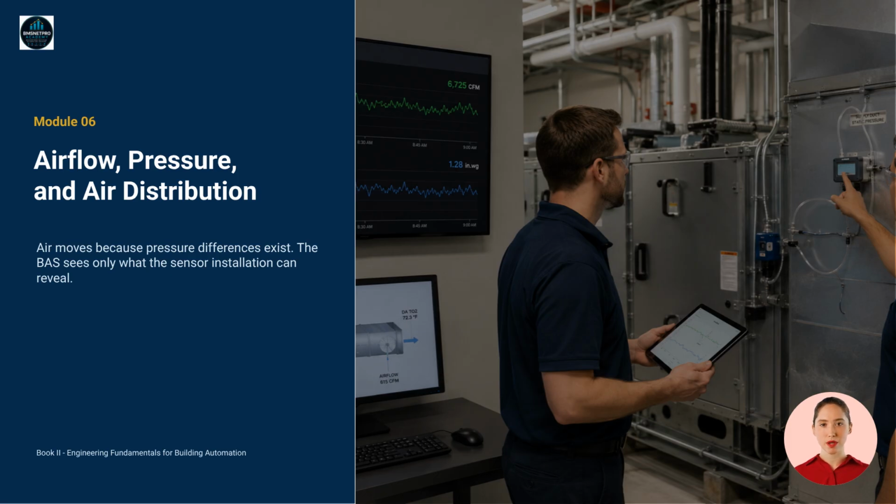Before changing a set point, verify the measurement. Where is the sensor installed? What is the high side connected to? What is the low side connected to? Is the tube clean, dry, and referenced correctly? A good BAS professional does not just trust the number. They understand how that number was created.